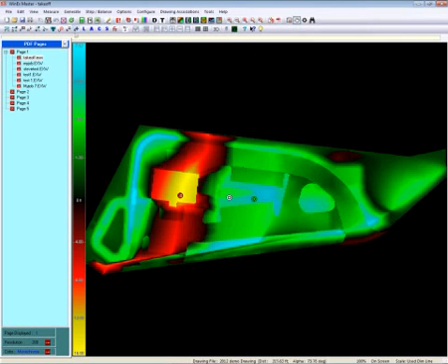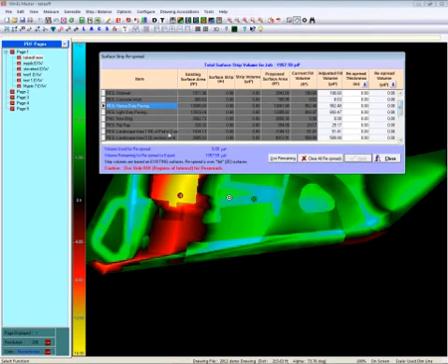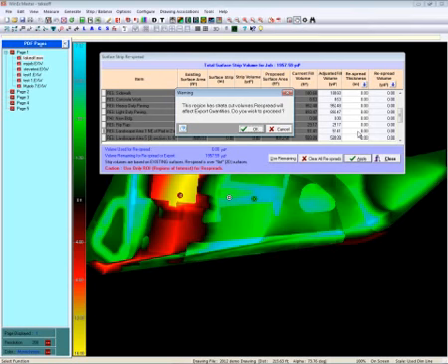And then, of course, I can come up to my strip and balance. I can come up to my strip and respread. And in this particular one, I set up several regions of interest that I call the landscape areas. The software is telling me I've got almost 2,000 cubic yards that I either need to export or respread. I don't have to tell you guys how expensive it is to export this stuff and how much those trucks cost and so forth. But let's say in landscape area 2, I've talked to the engineer and he says that I can respread some dirt around in there.